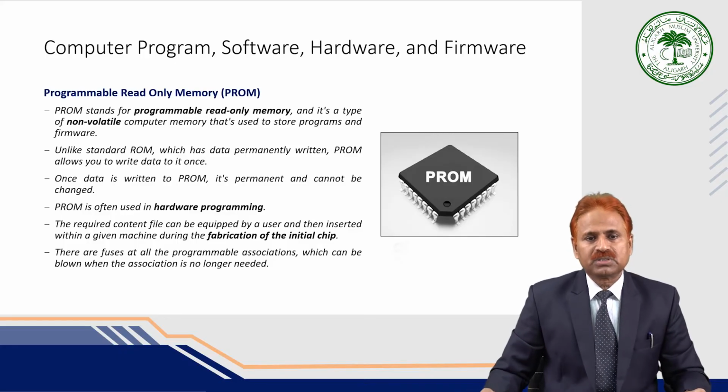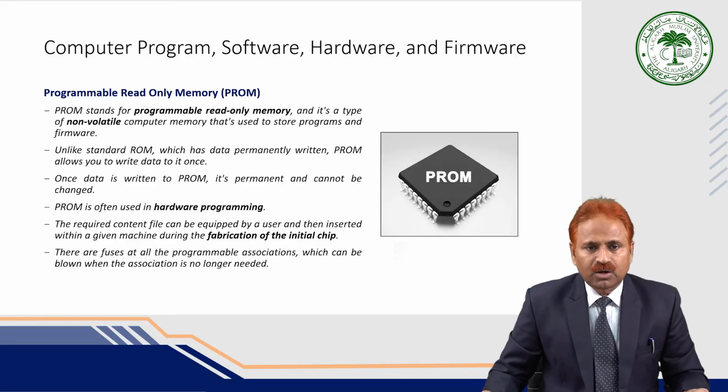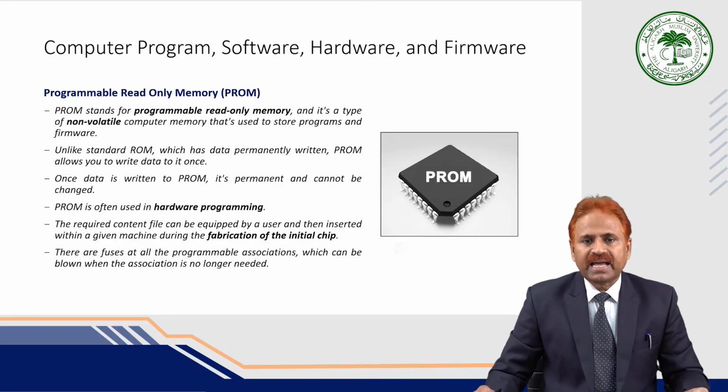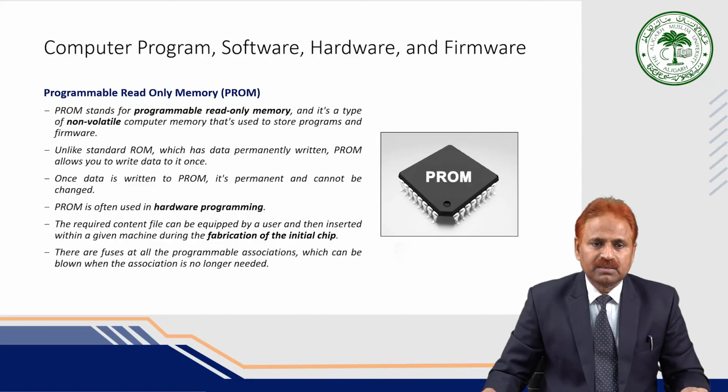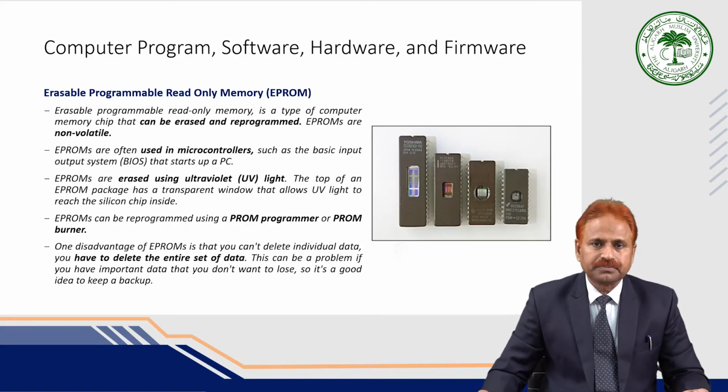PROM is often used in hardware programming. The required content can be programmed by the user and then inserted into a given machine during the fabrication of the initial chip. There are fuses at all the programmable connections which can be blown when the connection is no longer required.